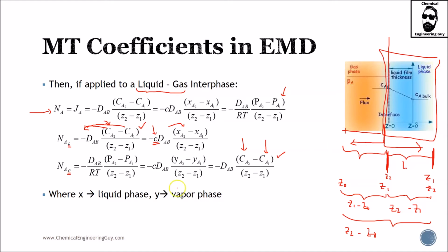of the liquid. For now, I just wanted to let you know that the flux of A in the gas phase and the flux of L in the liquid phase can be modeled as follows. And of course, you don't need to assume that these are the same, even though in some cases you can still assume it is true. Now, an important thing I want to show you is that whenever we're talking about molar fractions in the liquid phase, I will be using X. And when I use vapor phase, I will be using Y.